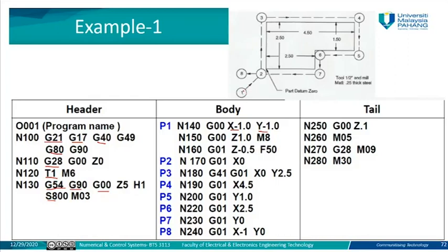if we do not consider the diameter of the cutter here, we just ignore it. So in this case, we just put the exact point of the spindle without compensating the diameter values. So the spindle here will move to the standby position, Z1, on top of the workpiece.